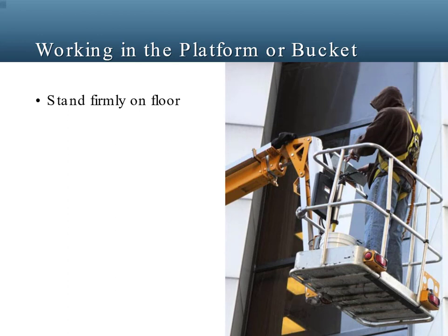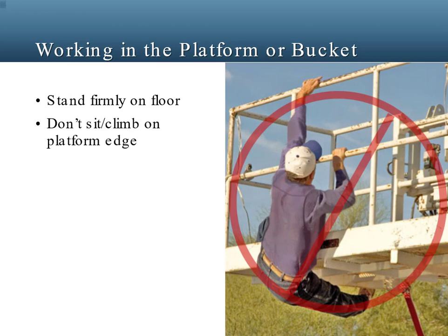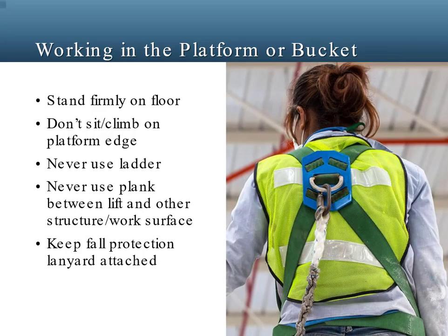When working in the platform, it's very important to always stand firmly on the floor. Don't get on your tiptoes or lean over the railing. Keep the soles of your feet flat while you are in the lift. Don't sit or climb on the edge of the platform. Again, keep your feet firmly planted on the floor. Never use a ladder in the platform to gain more height. Also, never use a plank to bridge a gap between the lift and another structure or work surface. And of course, keep your fall arrest system lanyard attached to the platform or boom at all times. Think about other precautions you need to take to prevent falls while working in an aerial lift.